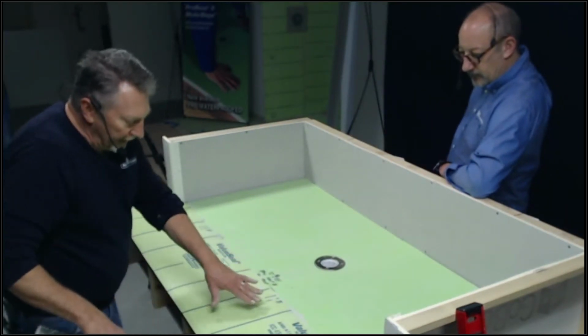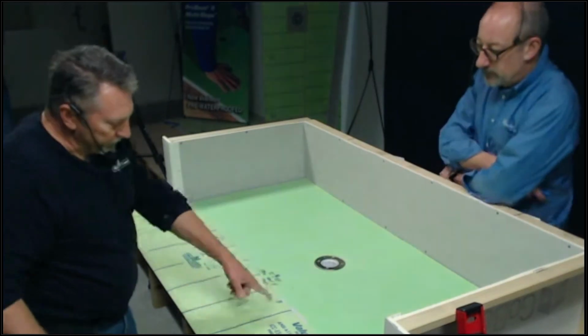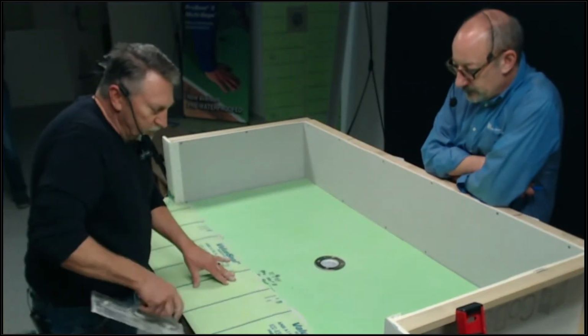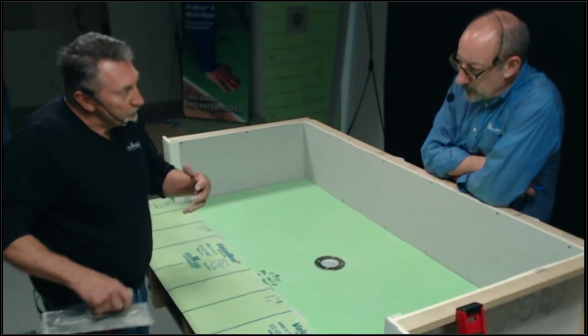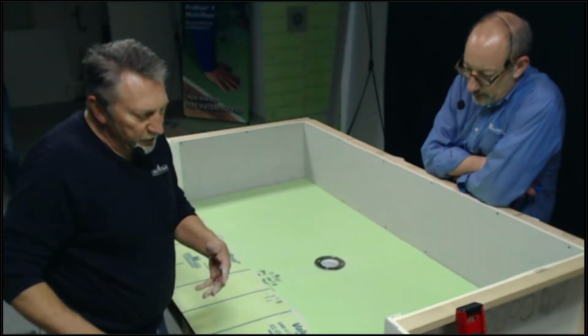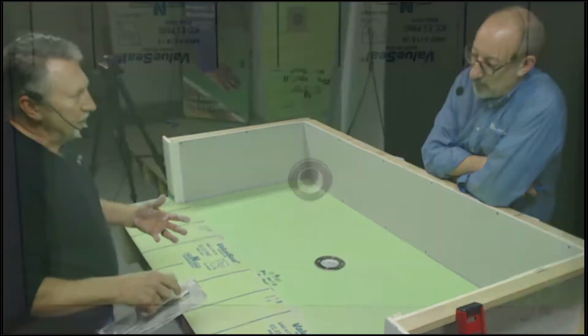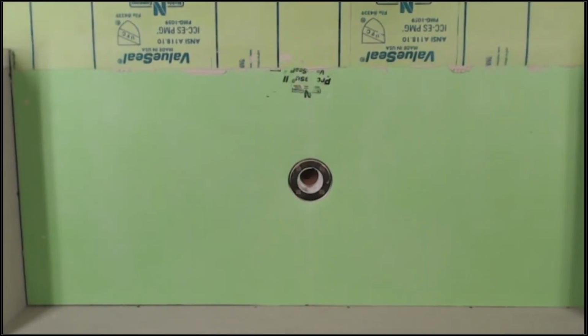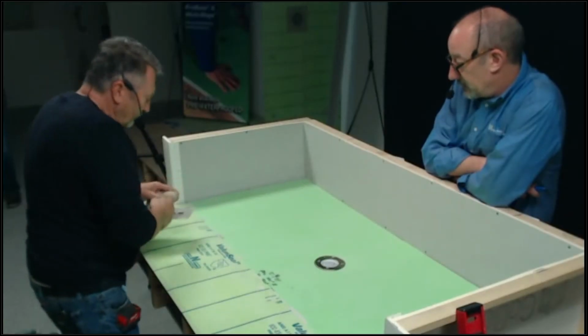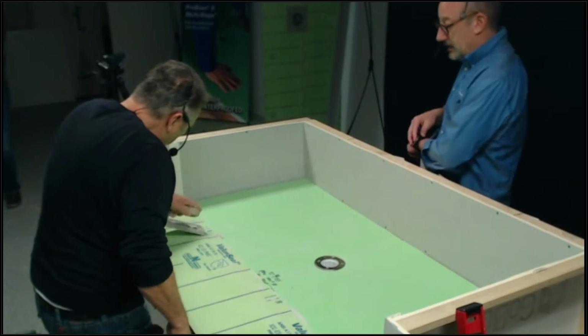So you can see the trowel marks in there right now, right? But as I tool that in, they disappear. So I'm getting 100% coverage on that. That's a great thing about Valu-Seal. It's translucent, so it's going to show you the transfer and how much coverage you have. Ideally, you won't see any trowel marks at all. The trowel marks almost look like shadowing. As Dave's embedding, it's just disappearing as he's knocking down the ridges.